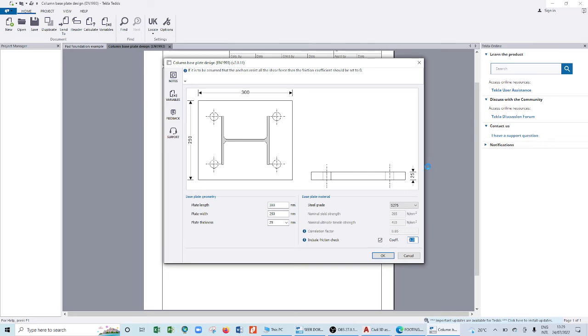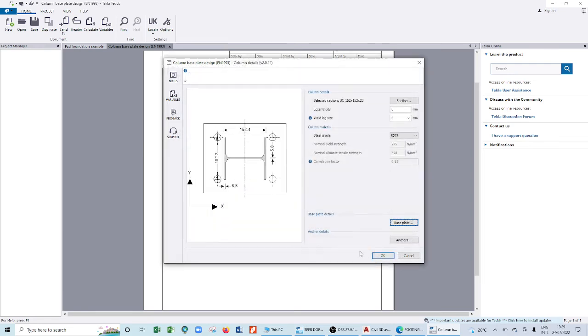If you're going to make it rough, you can say we are just going to do a rough concrete, so I can have just around 0.7, so it doesn't slide. Maybe rough, so I have 0.7. Or else, if you're not sure, you untick it and ignore it. Then you go to OK. Press OK.